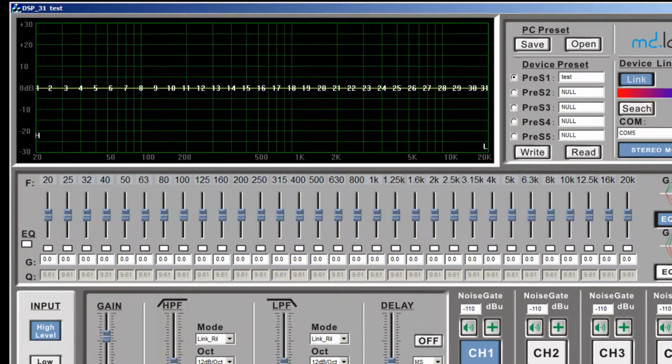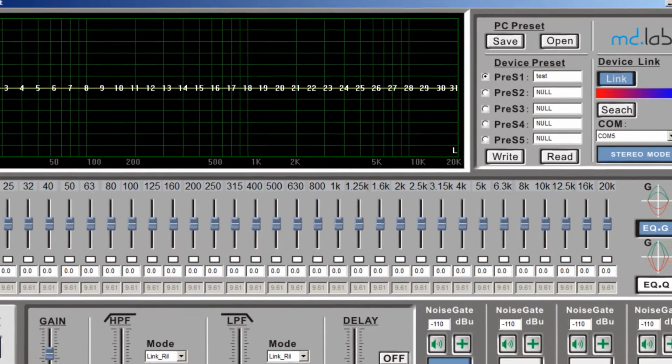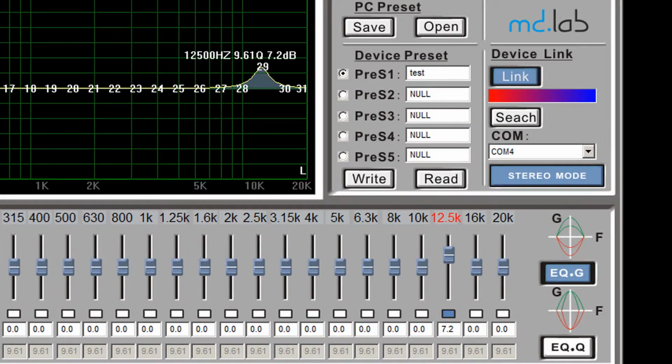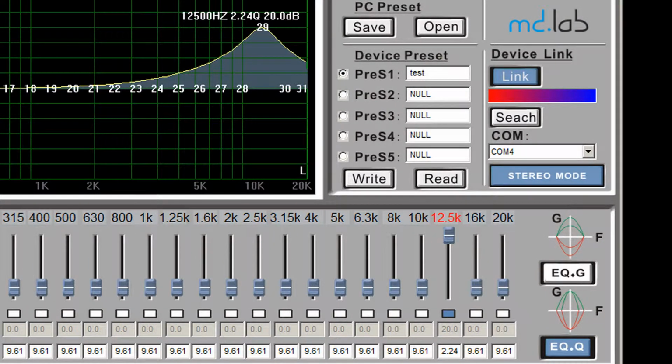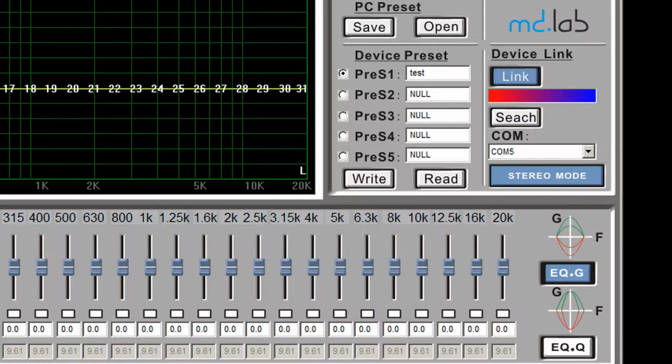Multi-band graphic equalizer, 31 bands with increments of a third of an octave, with the possibility of level regulation not only at each frequency, but also quality. Sometimes such equalizers are called paragraphic, as a hybrid of parametric and graphic equalizers. Level adjustment range is from minus 20 dB to plus 20 dB.